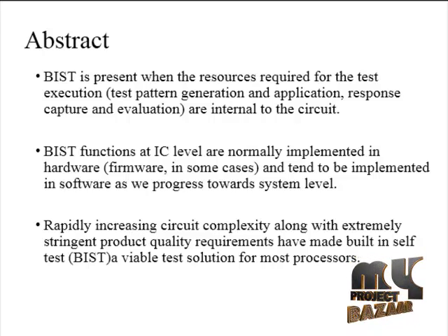The reusable CPGC IP is designed to connect to a standard IP interface, which enables a quick turnkey SoC development cycle. Silicon results show CPGC can speed up validation by 5x, improve test time from minutes down to seconds, and decrease debug time by 5x, including root cause of boot failures of the memory interface. CPGC is also used in memory training and initialization, which makes it a critical part of Intel SoC.